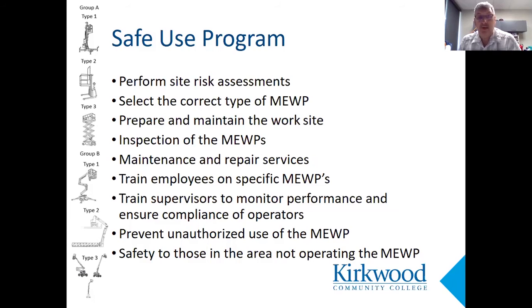Inspection of the MEWP, that program needs to be there. You need to have a daily inspection sheet, with whatever items you feel are important that comply with what the manufacturer recommends. Maintenance and repair services: if you've got your own shop that does maintenance or repair, make sure they have a good program, periodic inspections, maintenance of it, make sure everything's good to go. If you're renting equipment, you probably want to make sure they're doing what they're supposed to be doing, because that's your guys and gals up in those platforms.